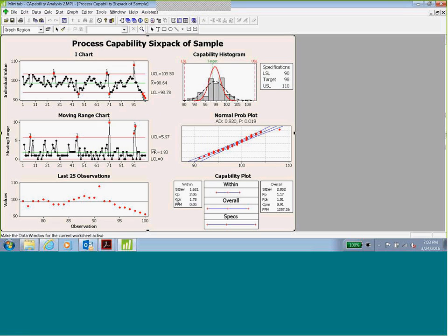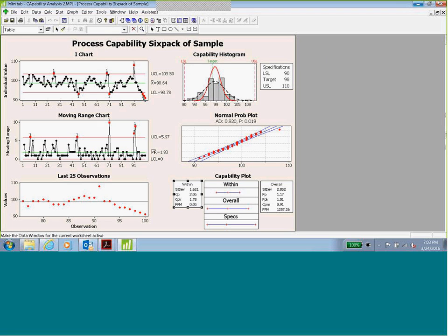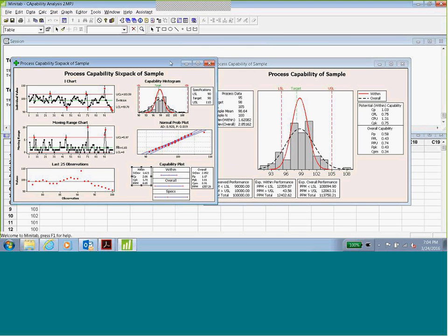You are trying to see your CPK value here. Okay, that's what the process potential study is about. So you are trying to see whether your process has the potential of meeting the specification in the short run, meaning with a minimum number of variations. So just with one production line, an operator, and a set of raw materials. Without more variations, you are trying to do the study and find out whether your process is feasible or not.